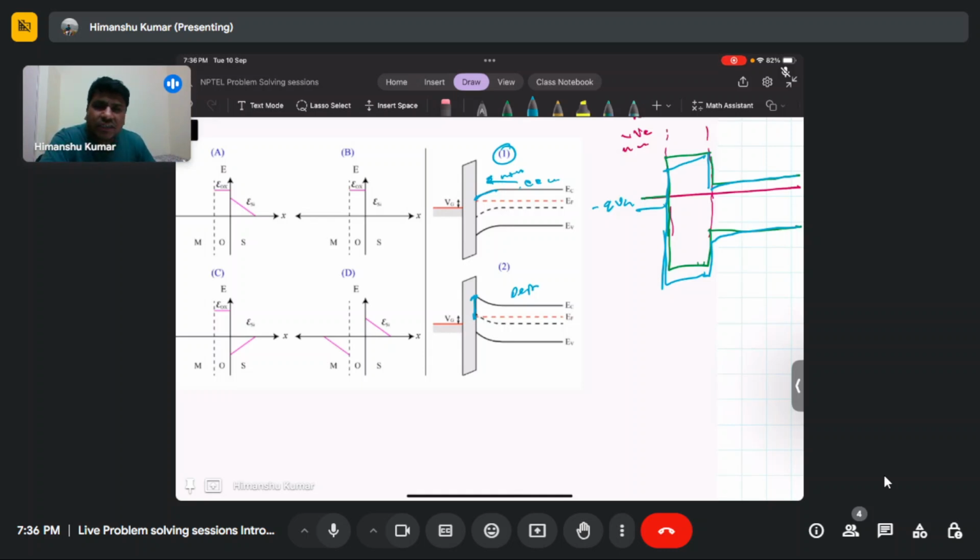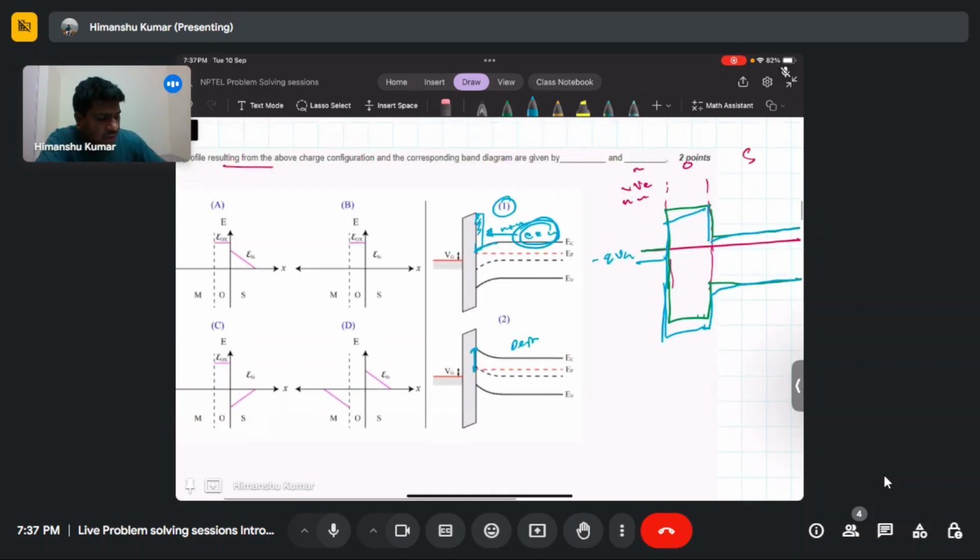Basically, in the semiconductor we have a huge pile of carriers available in the substrate, so we need to deplete only a very small amount of semiconductor to produce the charge we need. A typical doping concentration is 10 power 17 to 10 power 18 per centimeter cube, so roughly 10 power 17 electrons per centimeter cube are available.